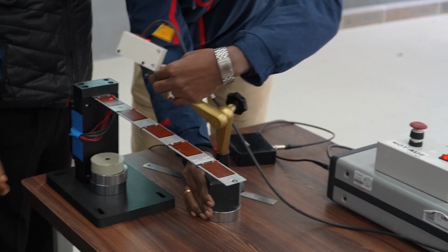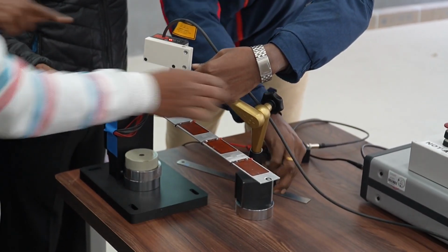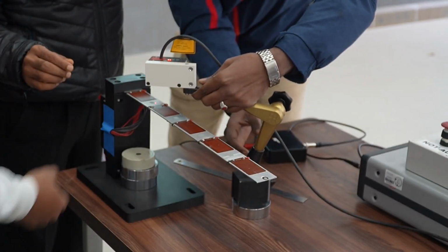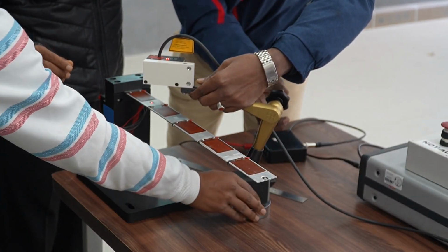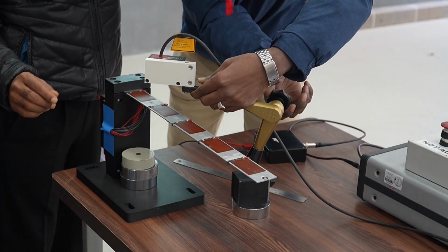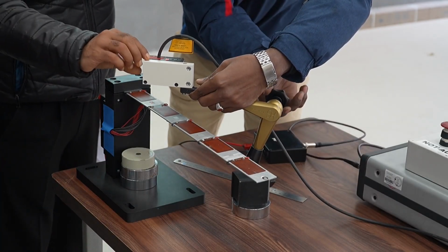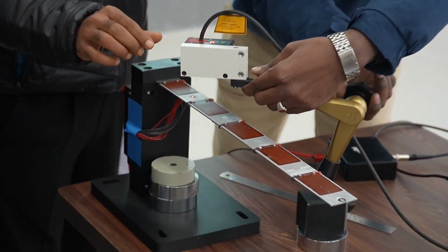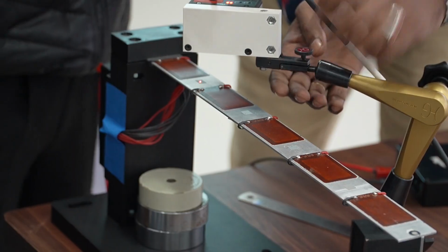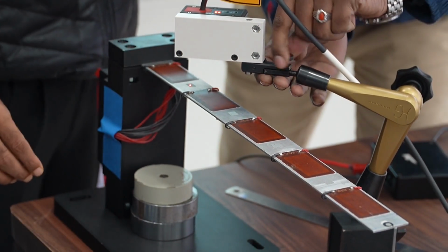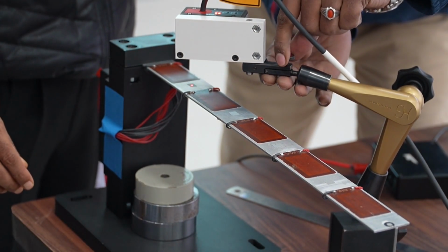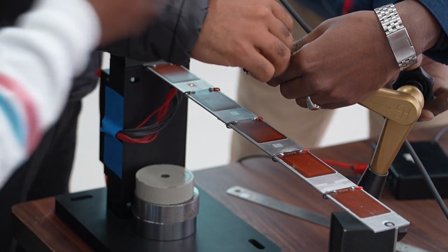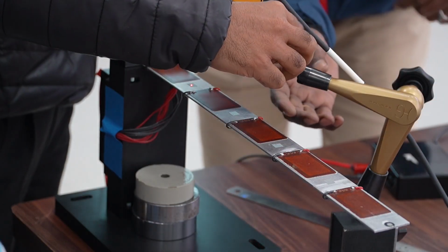And the maximum tip deflection will be whatever the laser is right now. Okay, and then again we do the difference by putting the tip deflection of the second to third by showing the laser, and then we'll subtract. First we will identify the first mode. Then we will plot the mode shape. No. First you identify first and second eigenfrequency, and then you identify the mode shapes by going into the first eigenfrequency and then into the second for each point. And measure the amplitude.